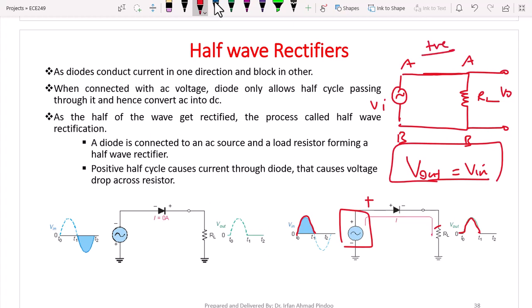In the negative half cycle, the negative voltage is provided, and as you can see in the diagram, this becomes negative. So we have a diode with this plus terminal and this minus terminal, and we are connecting the negative terminal of the battery with the anode. I have told it already, in a diode this is plus and this is minus. Now what are we observing here? It is a reverse bias being given, because minus is connected to plus and this is connected with the minus. Now in reverse bias, what will it act as? Insulator, meaning it will be an open circuit.